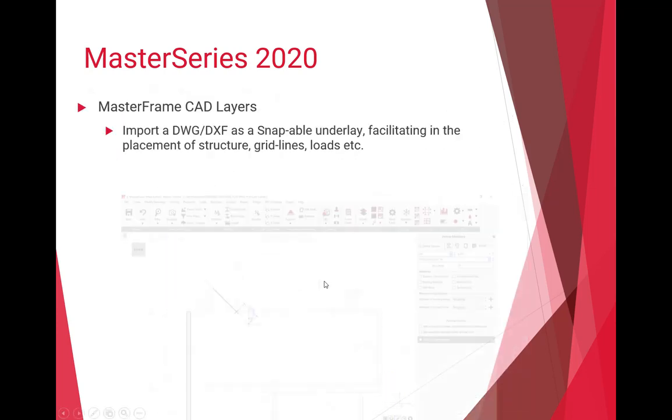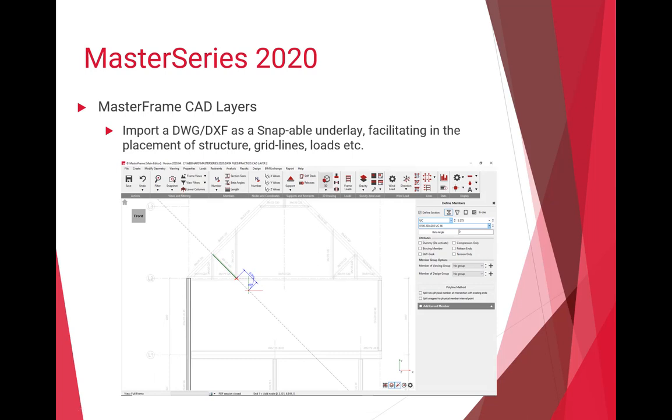We have a really cool new feature in MasterFrame called CAD Layers, and that's the ability to import a CAD drawing and have selectable, snappable entities from your drawing able to be drawn over. So that really does offer a lot of good facility in all the different areas of MasterSeries. You can snap onto drawing entities on this CAD layer, and you can have multiple CAD layers. Those can be anything that you want. Could be a floor plan layout showing your structural entities along with block walls for the placement of line loads. So the application of that is quite extensive,